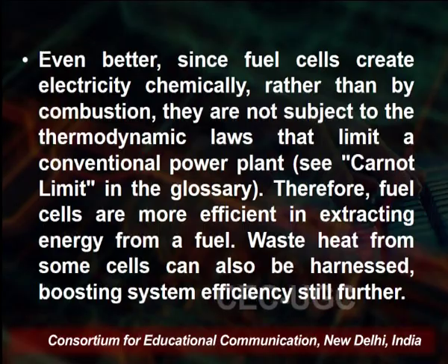As long as the fuel cell is supplied with oxygen and hydrogen, it will generate electricity. Once it is stopped, no electricity will be generated. Even better, since fuel cells create electricity chemically rather than by combustion, they are not subject to the thermodynamic laws that limit a conventional power plant.